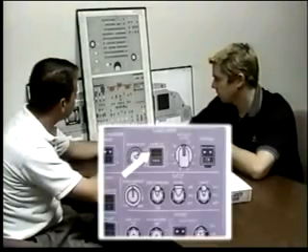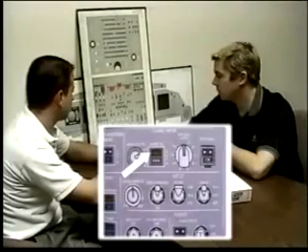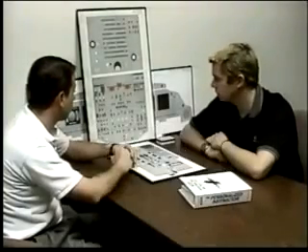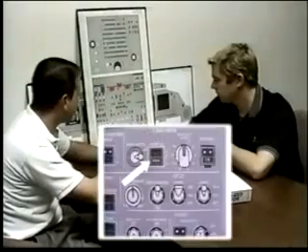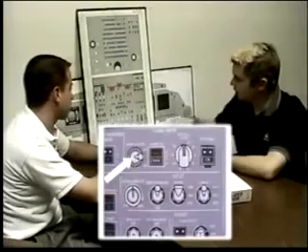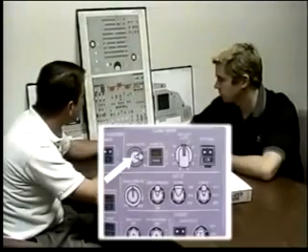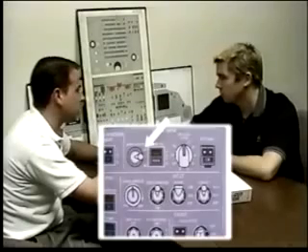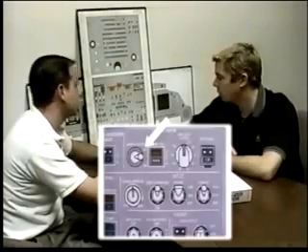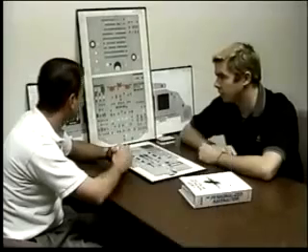You have a fault light on the mode select switch. What's happened here? That indicates that System 1 and System 2 auto pressure controllers have failed. Okay, so you select manual, and now how can you control pressurization? With the manual vertical speed control switch. You take the selector to up. What are you doing? Up means I want to raise the cabin altitude, so I'm going to open the outflow valve to decrease pressure.